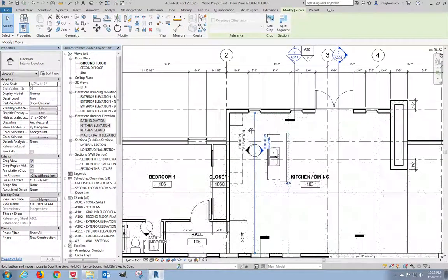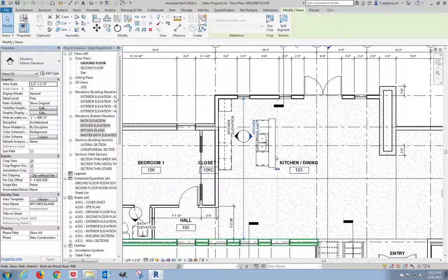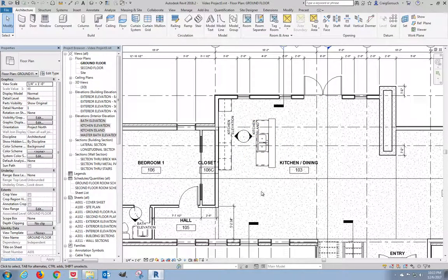If I were to show this entire elevation, but only give you pertinent information about the cabinet, you do have a lot of empty, vacant white space, a lot of naked elevation on your sheet. So I'm going to pull this line back just so the extents of my elevation don't reach so far out. Okay, those two things really did need to happen.